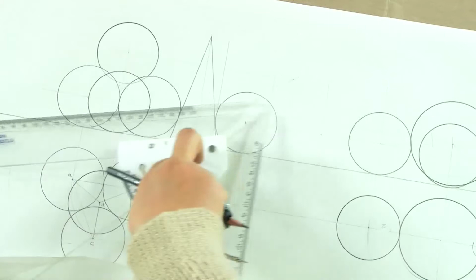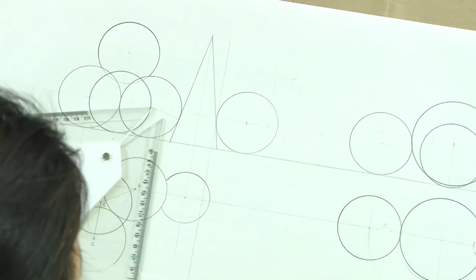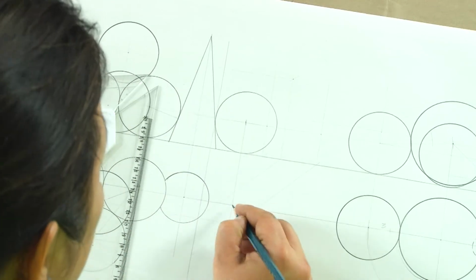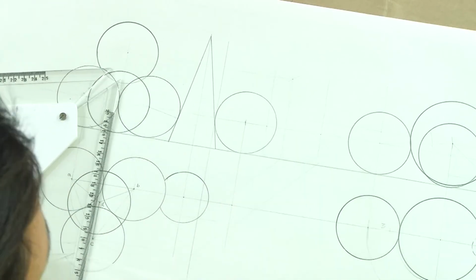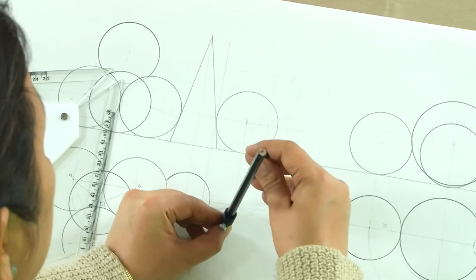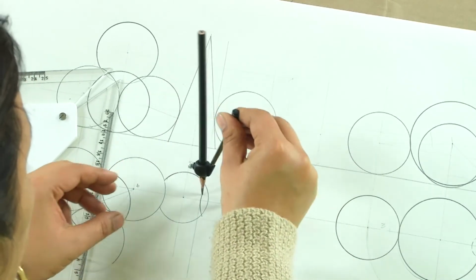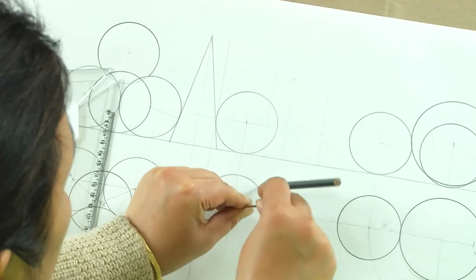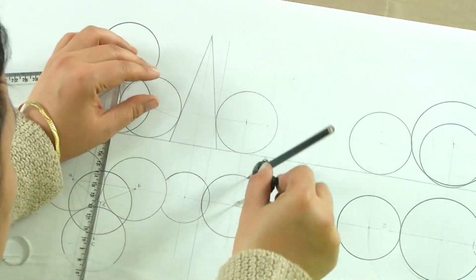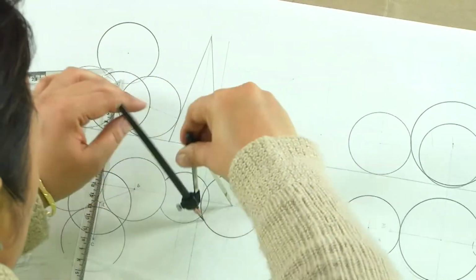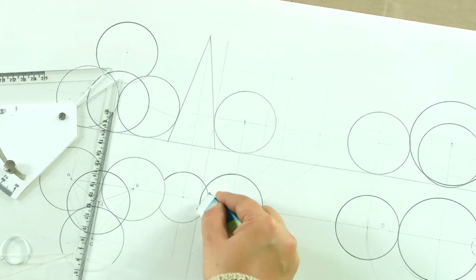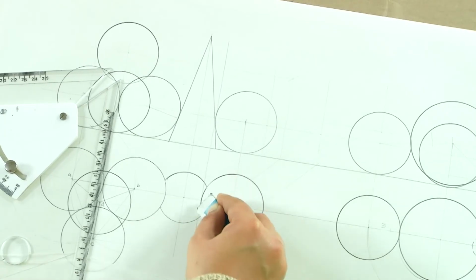And this is what the other sphere would be. We will again locate the center of this and draw it in the plan. What you see in the plan is that this sphere again overlaps the cone, so we will actually not see this part of the cone again.